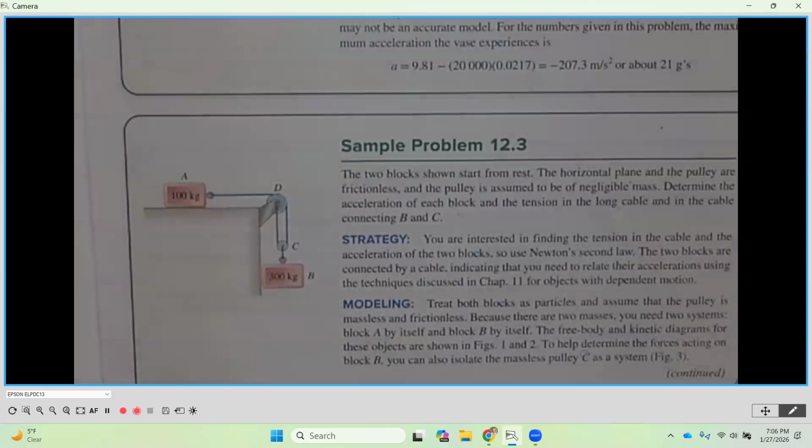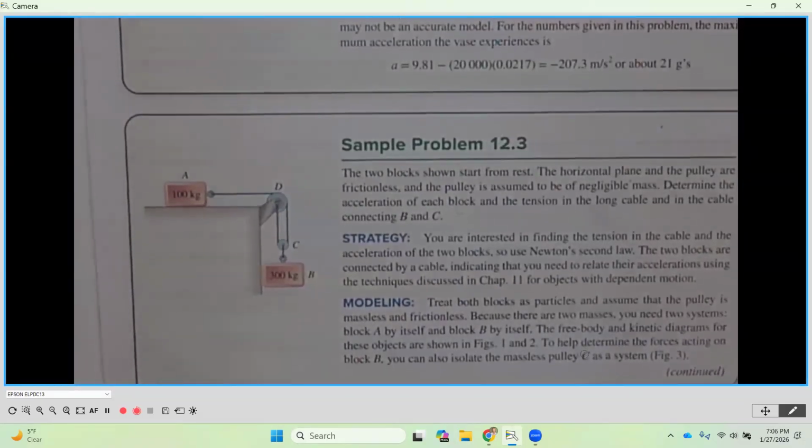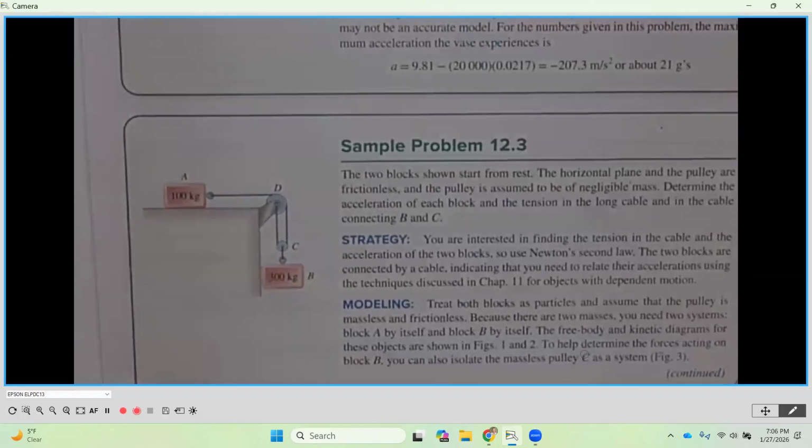You not only saw mechanical advantages as far as the input force that you could gain, but you also saw distances change. Your give up was usually distance. If I could pull on my pulley string and lift a large load with a small amount of force, the difference was I had to pull a lot of string through my fingers for the load to go up only a little bit. Do you guys remember that? And that all was dependent on how many wraps around my pulley there were.